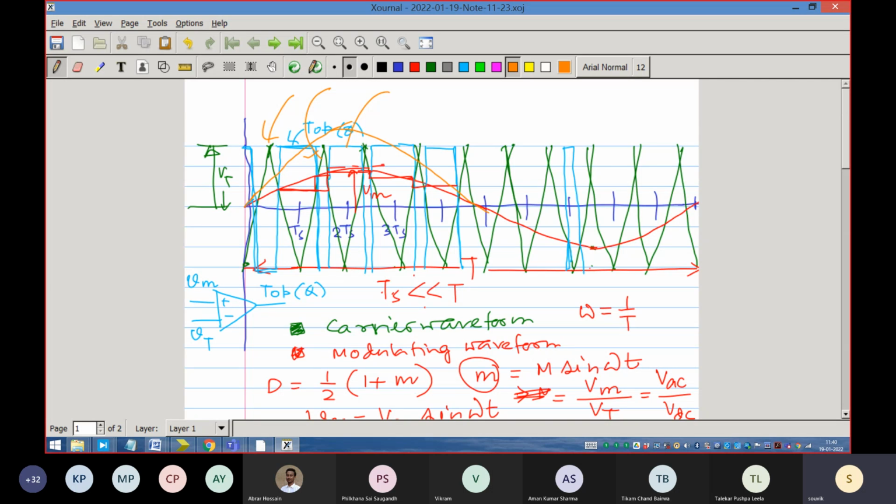So in what other way can it be different? It cannot be different. There cannot be any harmonics in that. The only harmonics may be high frequency harmonics, the switching frequency harmonics, which don't cause much problem, because the motor's leakage inductance will filter the current due to them. I'll give a much better explanation later, but you develop your common sense.